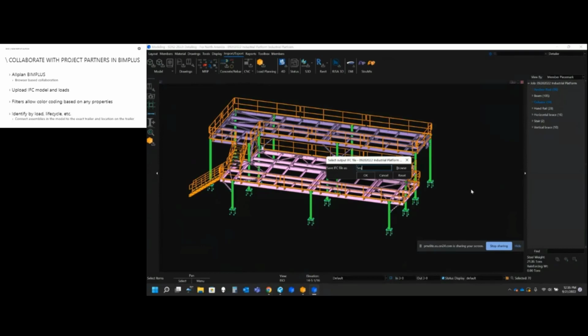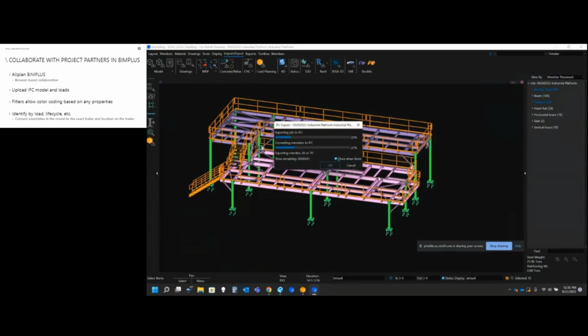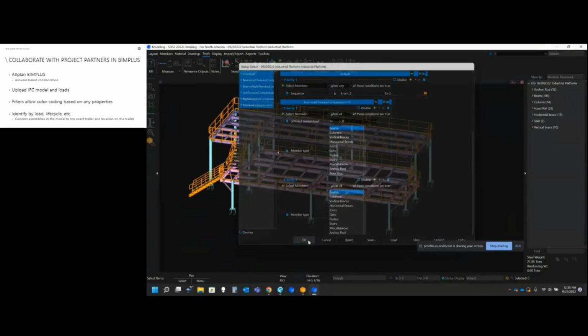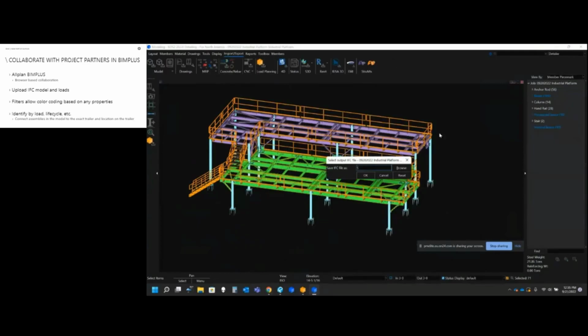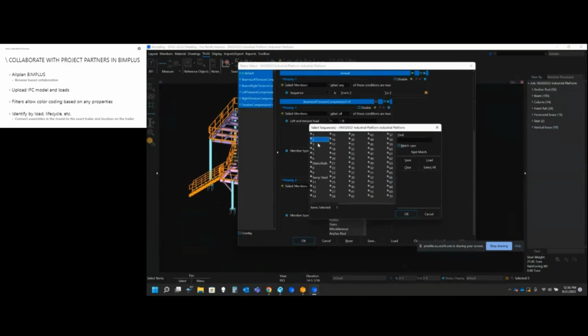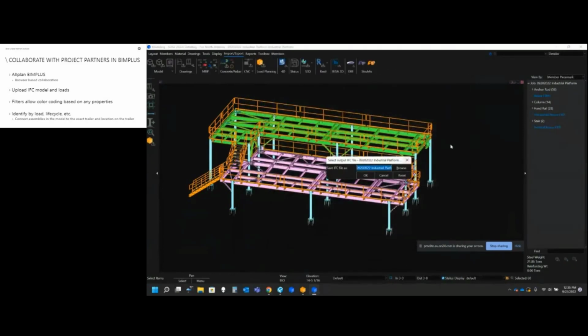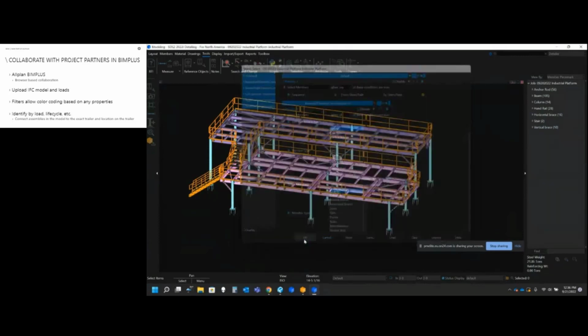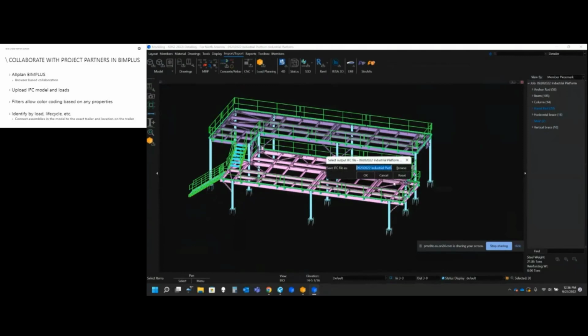So I'm going to call this sequence 1.IFC. Okay, and then I can run my status select again and change my sequence to 2, grab sequence 2 for me, and run this export again. I'll call this sequence 2.ifc. Okay, run my status select again on sequence 3. There we go. Load planning export, sequence 3. And finally, one last time, status select, select all my stairs and rails. Got those. And then I can do the export one last time. I'll call it stairs rails.ifc.